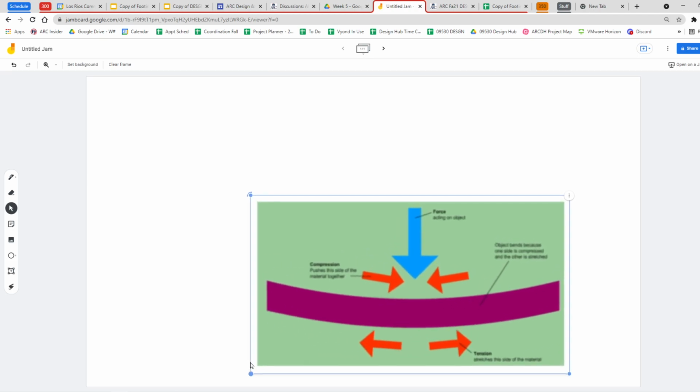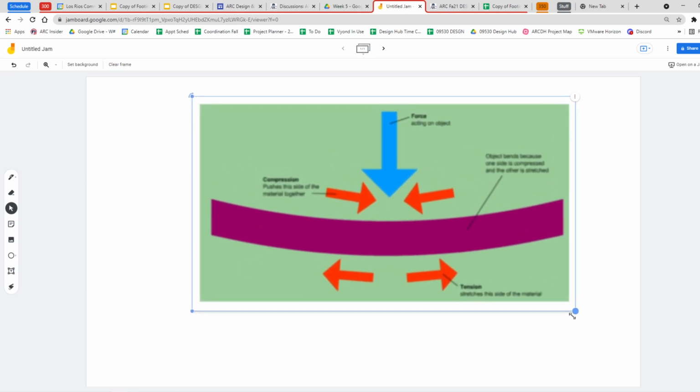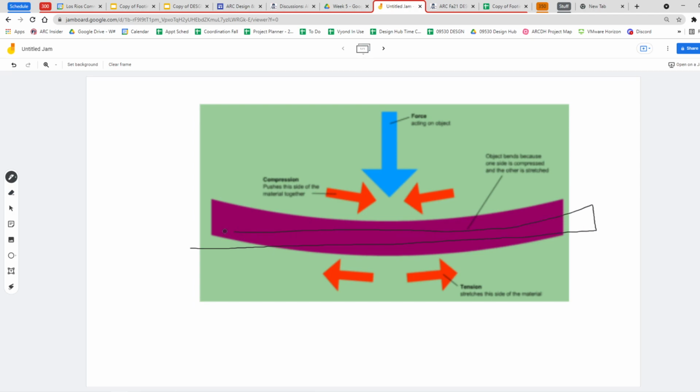So this purple thing, that's a footing, and it started out flat. Started out like that. And then there's some sort of loads that are on it. And it just literally bends. Because although there's supposed to be ground under it all over the place, you can get voids where something's dug it out, or it's just subsided, or it shrunk away, or some water has eroded away.